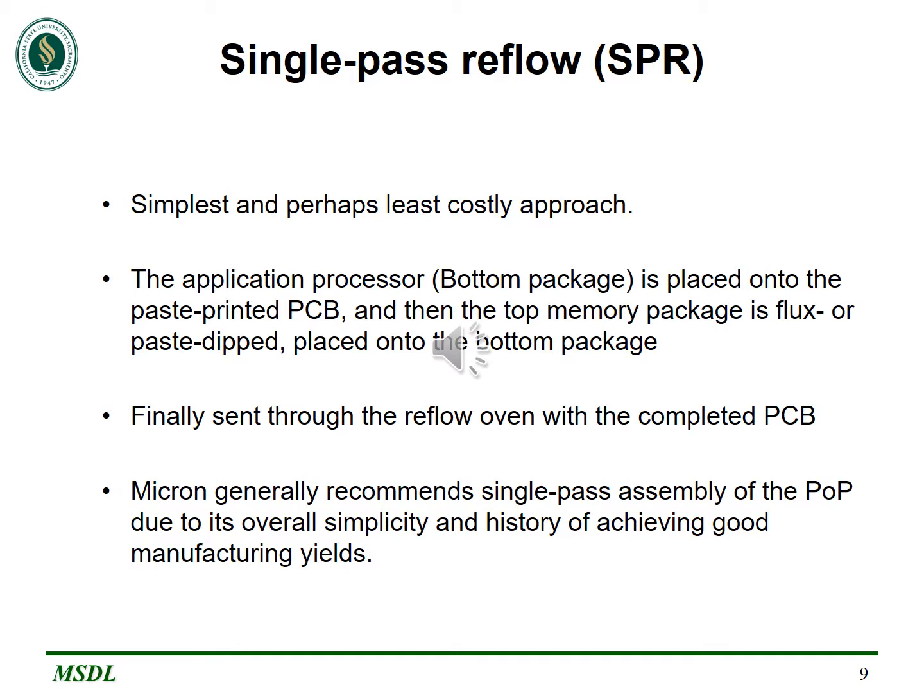It is the simplest and most cost-effective method. In this method, high-density digital logic devices, that is bottom packages, are first pasted onto the printed PCB board, and then the high-capacity memory devices are placed onto the bottom package using the flux or paste dip medium. Then the whole assembled part will be sent through the reflow oven. Because of this simplicity and good manufacturing yields, it is the most recommended industrial method.